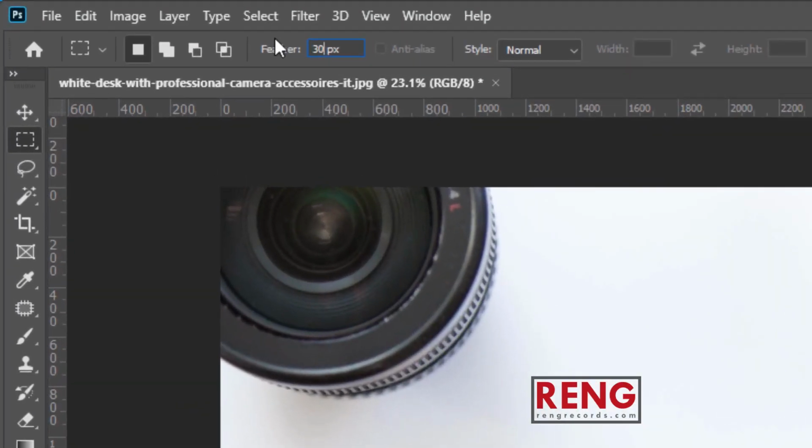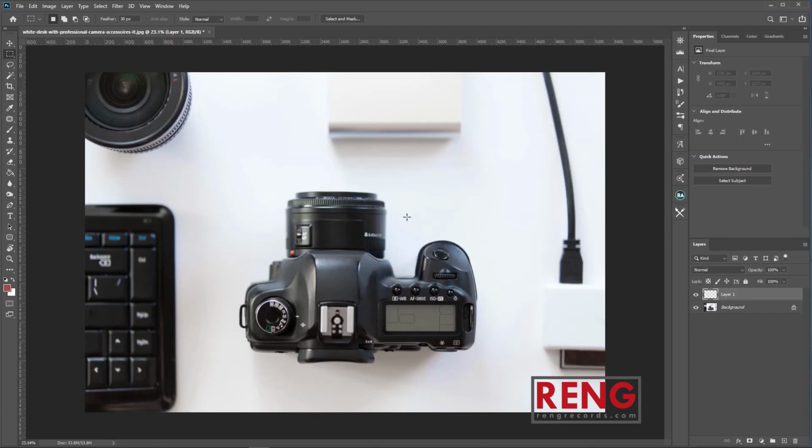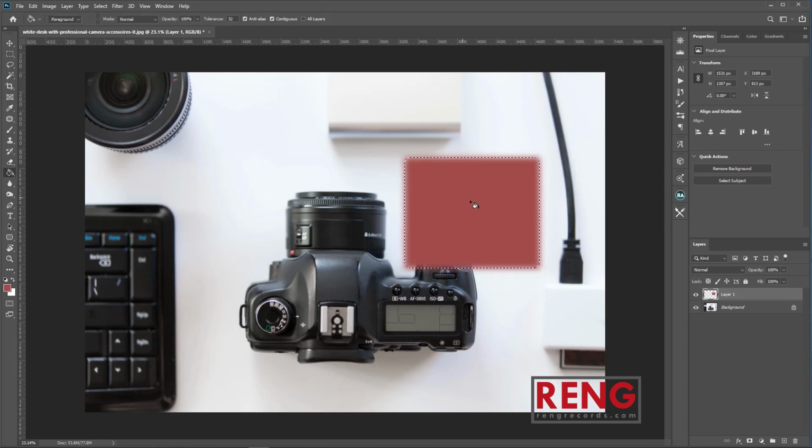Feather, from the options bar, determines a scatter around the selection area when moving or copying to another location. If the feather is 0, the selection border is quite sharp. But if it has a value, there will be no clear boundaries for the selection area. To understand the subject, pay attention to the following figure.